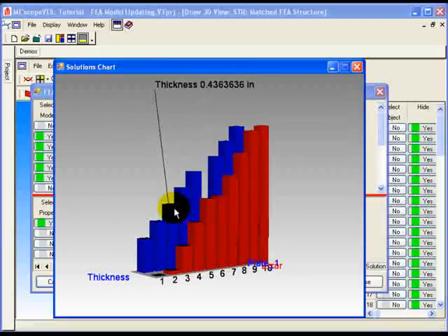This is the expected result. All of the 10 best solutions include a plate thickness greater than the current thickness of 0.375 inches. Solution 1 has the smallest error value, meaning that a thickness of 0.4303 inches yields FEA modal frequencies and mode shapes that are the best match with the EMA frequencies and mode shapes for the first 5 selected modes. Any of the 10 best solutions can be used to update the FEA model and calculate its new mode shapes.